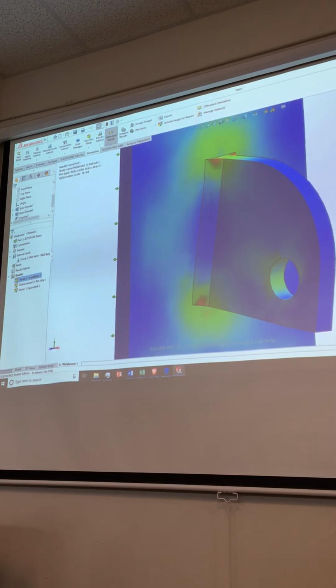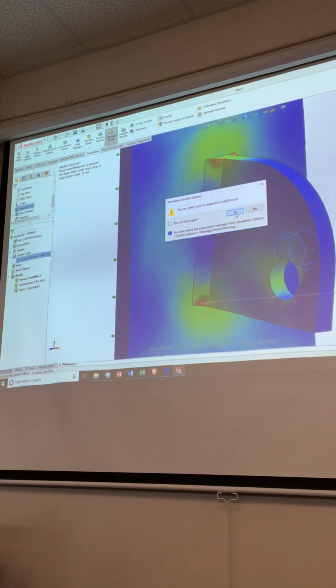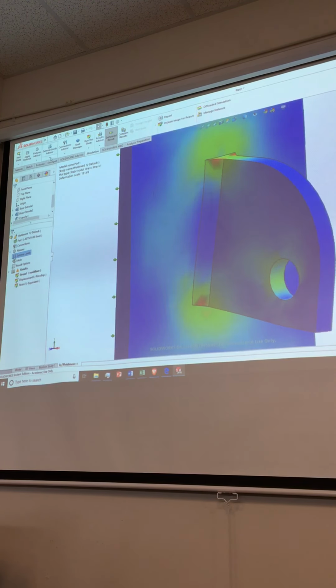And that's because, of course, I did a force thing, and then you remember that, wasn't that professor saying something else about there are other things you could do there? And so let's delete that darn thing, if that's a wrong thing to do. So how about forces? What else could we do? Bearing load. Ooh, bearing load. And if we do a bearing load, the first thing it wants is a coordinate system.